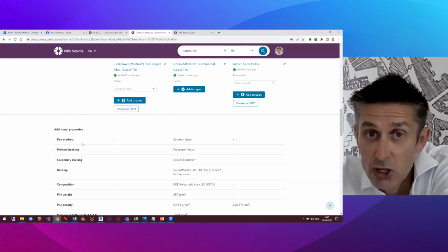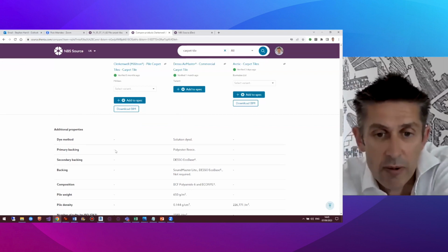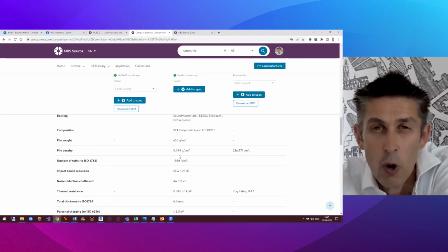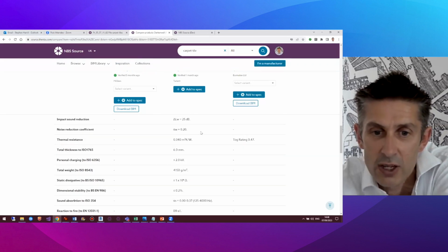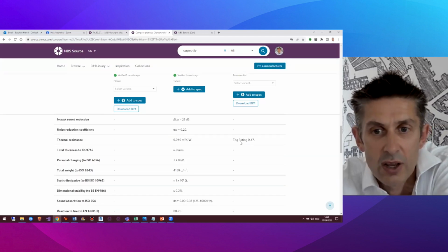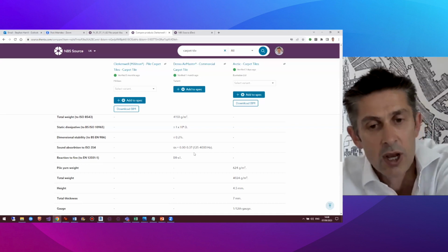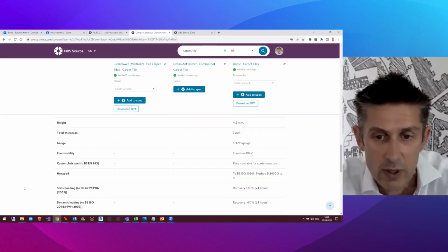Manufacturers will also want to add additional properties that distinguish them from their competitors, and you can see the additional properties there over and above the NBS specification templates as well. Maybe they don't quite have that consistency. For thermal resistance, you've got the manufacturers Target and Thermatex just declaring that in different units and values. But for the NBS ones, we've standardized them, the NBS defined ones.